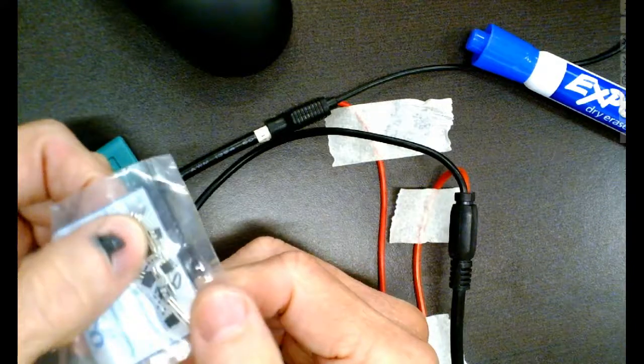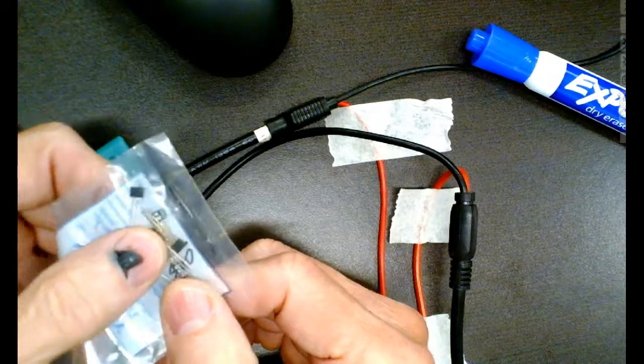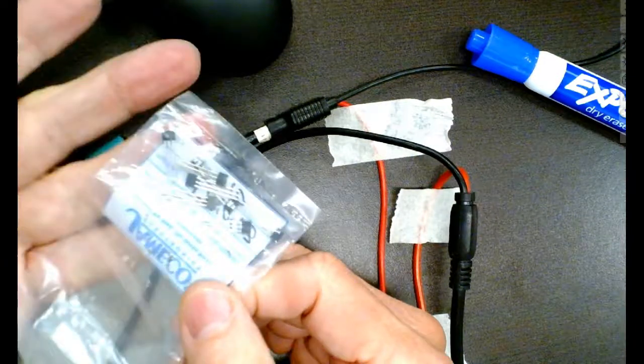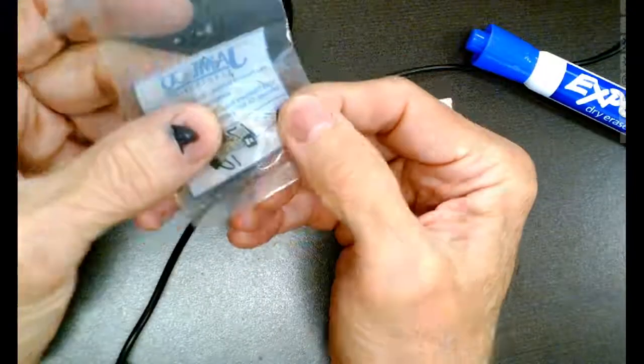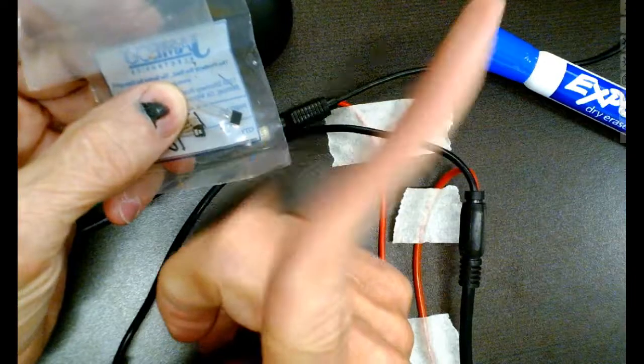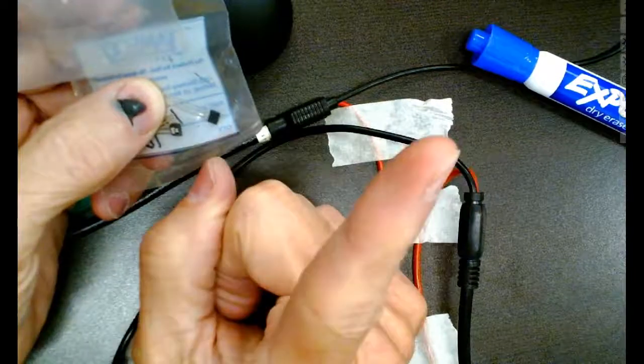And what we'll do is we'll see them next class. I'll have them hooked up over there so y'all can actually see these things work. But these are called Hall effect sensors. And what do they do? Notice they got 3 pins. Why do they need 3 pins? Power, common, and... 2 for power, 1 for what? Signal.